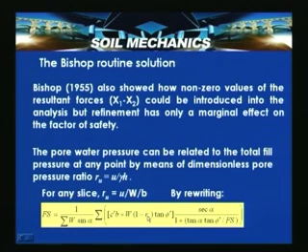So, here this particular r_u considers the effect of the pore water, the phreatic line within the slope. If the phreatic line is far away from the slope, say for a road embankment constructed on a foundation soil, in such a situation if the groundwater table is far away from the slope section, we can assume r_u is equal to 0.